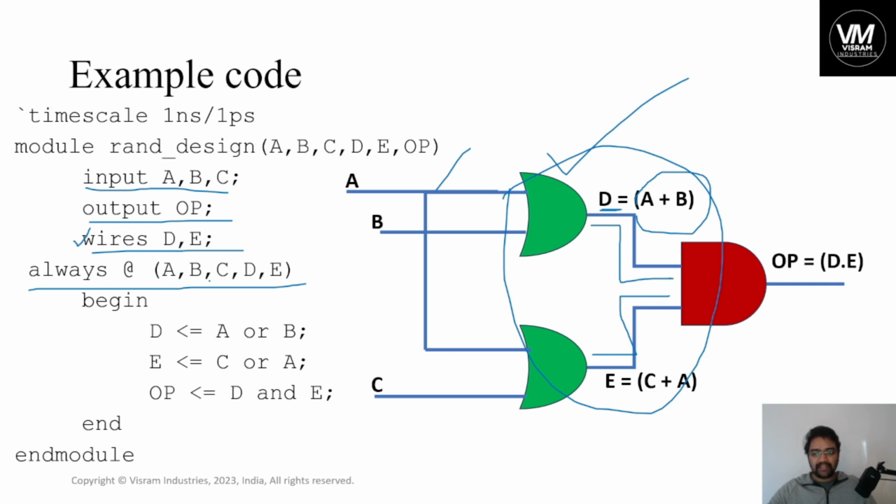When you set it as always @(inputs) at the input data flow, if the input data changes, then it works. If this is 1, it will work, and if it is 0, it will work again, and if it is 1 again, it will work. Unless there is a change, if it is 1 and stays 1, it won't change at all.